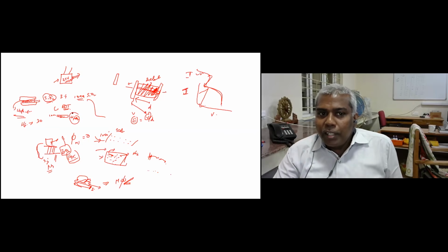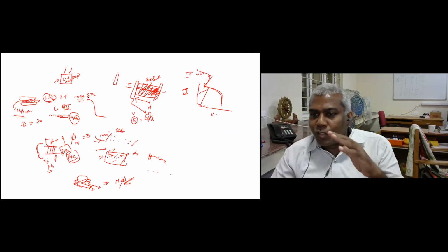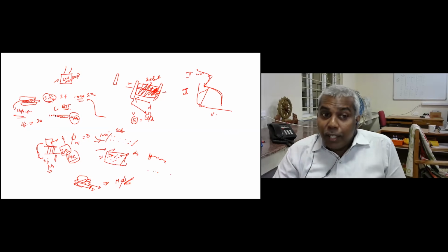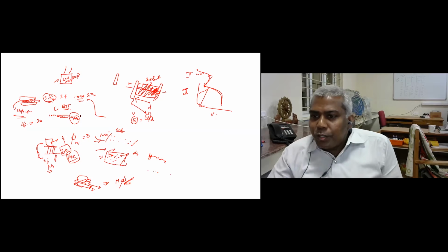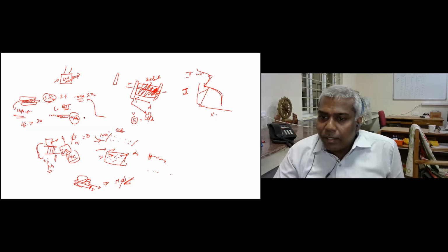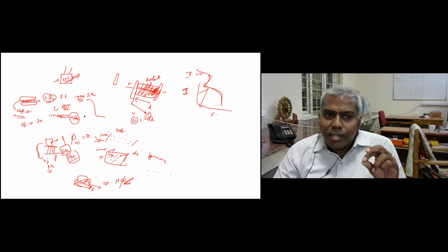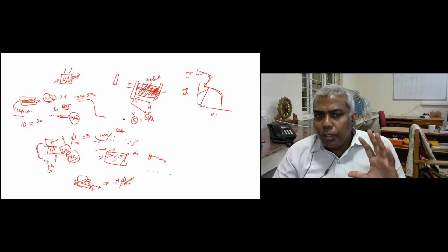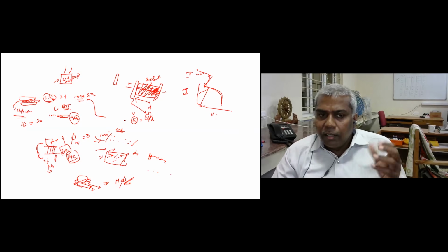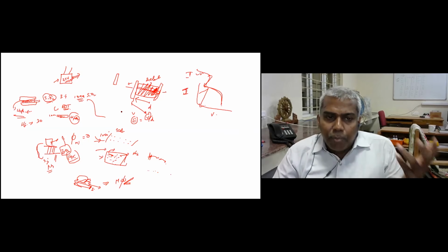So 1 nanometer is behaving like 10 nanometer of silicon dioxide, but 1 nanometer is the physical thickness I quoted. If hafnium oxide is not interesting, well, hafnium oxide is actually good. Many people are doing research on different types of materials with very low leakage current. They coat this, make a MOS, and measure the IV, and they will say, okay, what is the leakage current? Let's say femtoampere, nanoampere, picoampere, whatever it is.